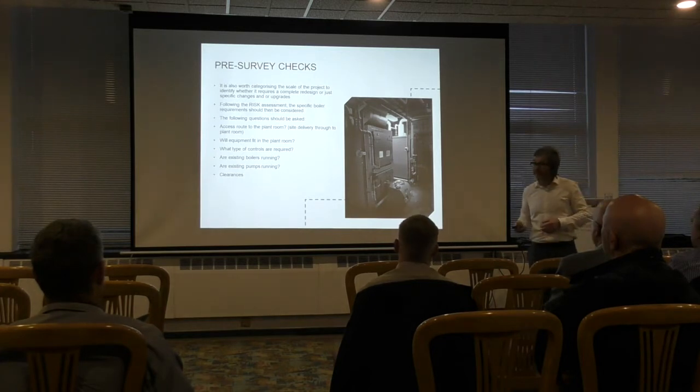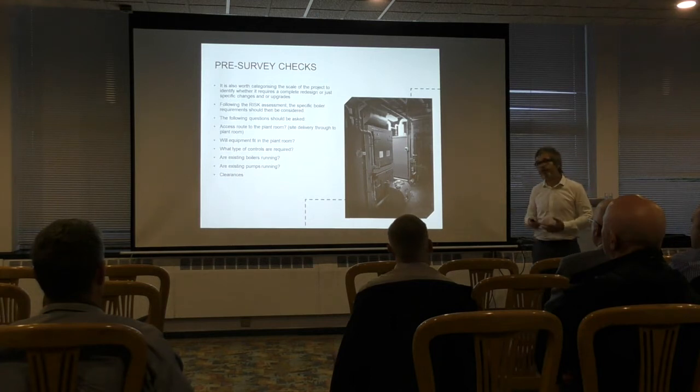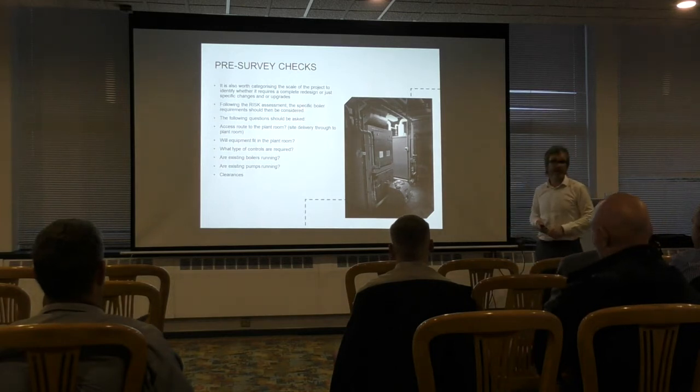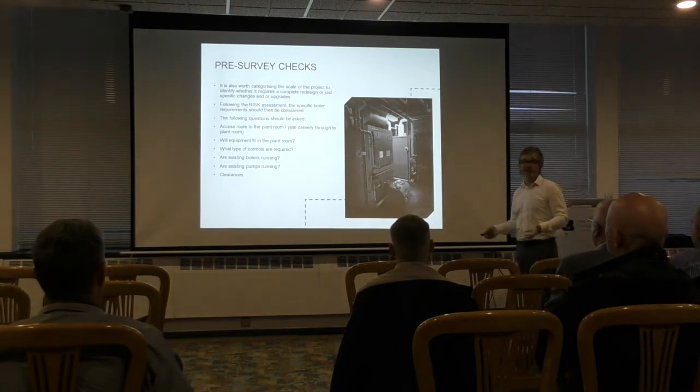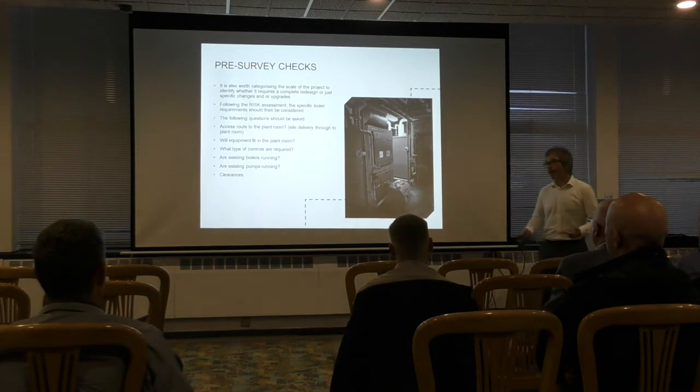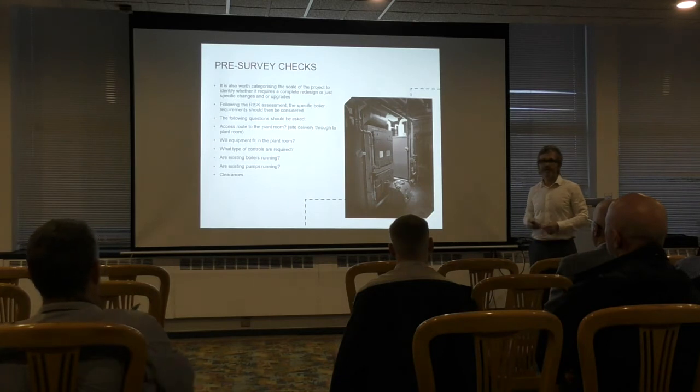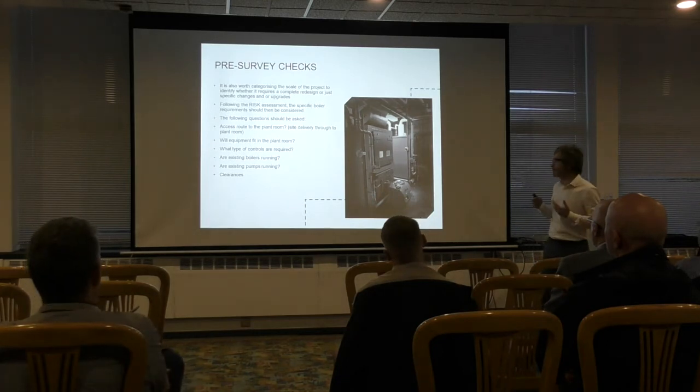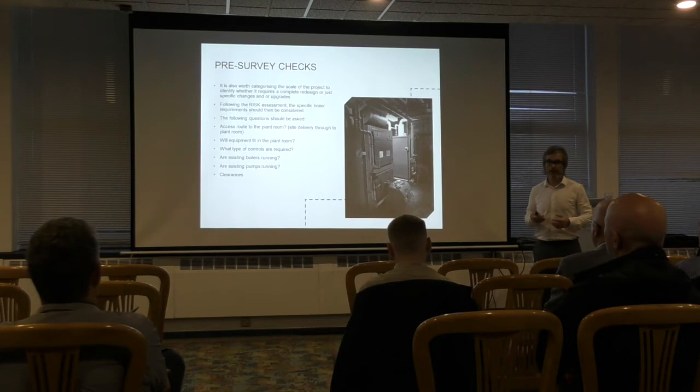And finally, clearances. Any bit of plant, every manufacturer would specify clearances around it, and boilers are no different. The main reason we specify those clearances is so we can service the boilers and replace components. Chances are if you butted boilers right up against each other, they'd probably work fine, but we wouldn't be able to service them. And if we can't service them, can't replace any components, then the longevity of the boilers is going to fall through the roof.